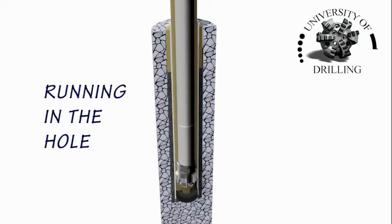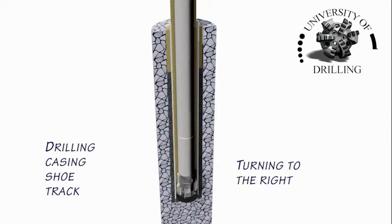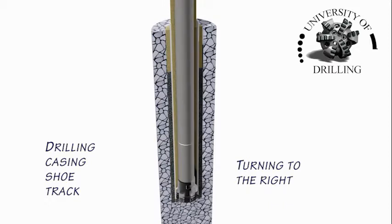A drill bit and drill string with diameters suitable for fitting through the previous casing and capable of drilling the next hole section is then run in the hole. First, the drill string must be turned to the right to bore through the previous cementing plug, and any remaining cement in the casing shoe track.